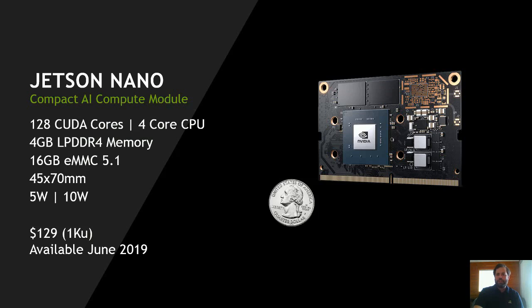So I mentioned that the developer kit includes a Jetson Nano compute module and the reference carrier board. Jetson Nano is actually a 45 by 70 mm embedded module that can be integrated into production products and devices. The compute module contains all the processing, memory, and storage on board, and it provides all the I/O through its 260-pin SODIMM style edge connector. Embedded system designers can design their own carrier boards from the reference carrier board included with the dev kit that routes the I/O to the connections and ports that they desire.